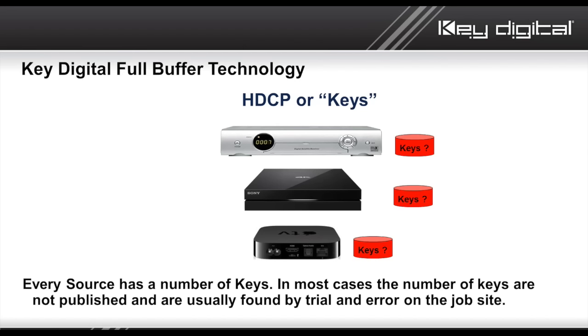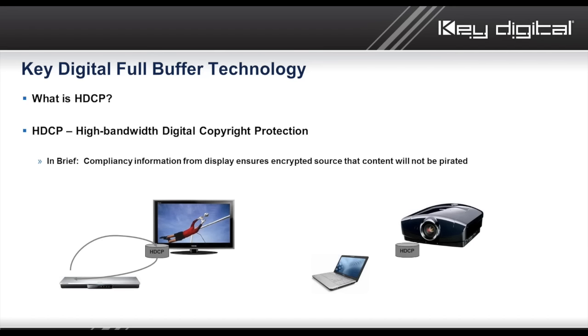and that's basically the source asks the display, are you HDCP compliant? In other words, are you going to pirate my content? And the display must return and say, no, I'm not going to pirate your content. You can output. Here is your compliancy. Now, we see it on the consumer devices, but we don't really see it on the professional devices like laptops and PCs and that kind of thing typically. But all HDMI connectors, regardless of if it's on a consumer device or a professional device, all HDMI connectors support HDCP and could support HDCP if that encryption was added to the signal, if you will.